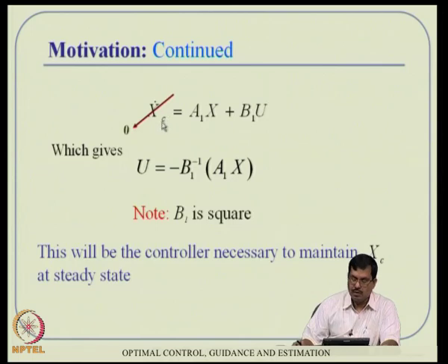So that my aircraft continues to fly steady and level basically. That particular control is actually necessary for maintaining x_c dot = 0. If x_c is h dot, for example, and u is delta E, the elevator deflection, then I have to compute this elevator deflection that way, okay. So obviously we require this type of solution.